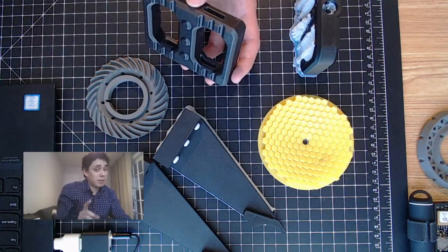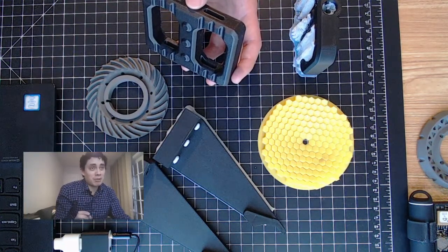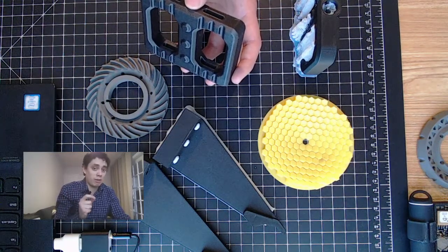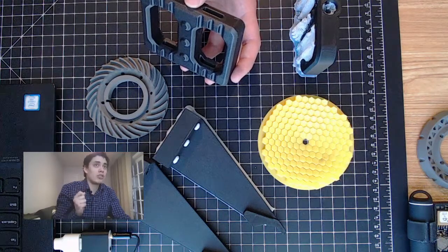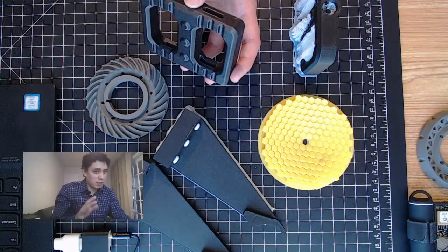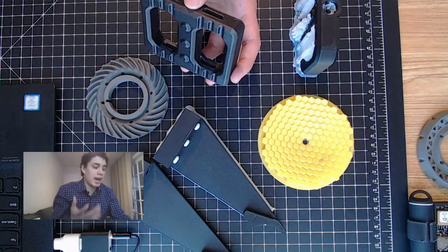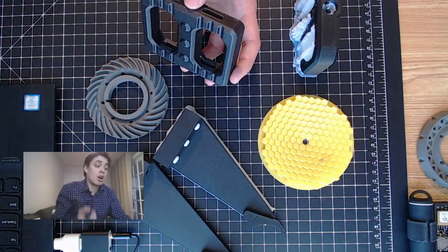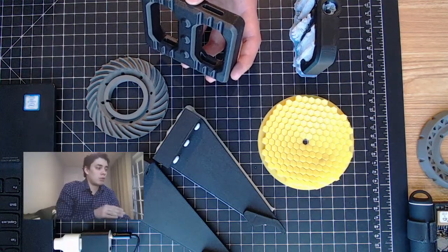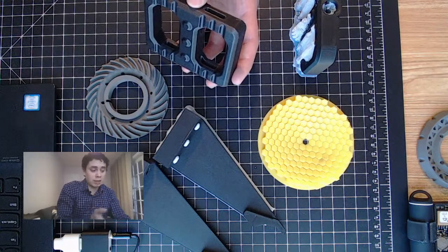So anybody who's promising less than 100 microns layer resolution, I would be aware of that, because unless you're using a laser printer, in which case it can be a little bit more manageable, it's really tricky. And not only that, it'll add a lot of time to your print. So bottom line is, usually you'll see somewhere between 100 to 200 microns for the layer height.